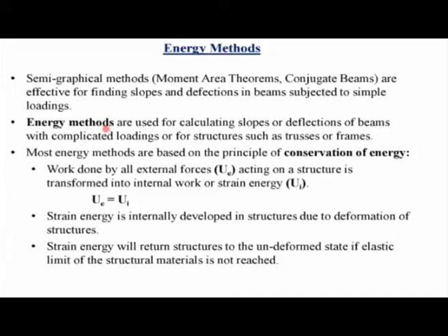And the energy methods that we'll cover today will be used for calculating slopes and deflections of beams under complicated loadings, and also in structures such as trusses or frames. These trusses deform mostly due to the axial deformation of the truss members. The frames deform due to axial deformation, bending deformation, as well as shear deformation of the frame members. So if you want to use the semi-graphical methods for calculating the deformation of trusses, it will not be very useful because semi-graphical methods are based on the elastic beam theory, which takes into account the bending deformations only.